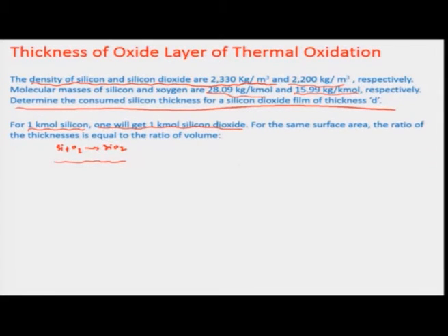If we consider a wafer like this, there is going to be a diffusion of the oxygen starting from the top end, the area where the oxygen diffuses and later on the oxide grows. So, the oxide would be based on the penetration and the percolation of the oxygen. Let us say there is a layer thickness of D which has been arrived at because of such percolation and penetration.